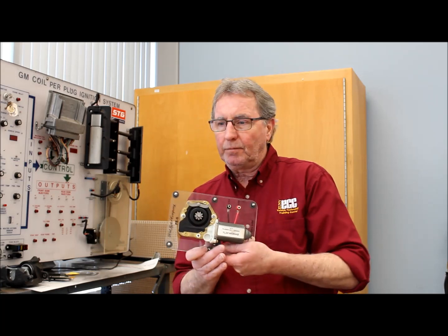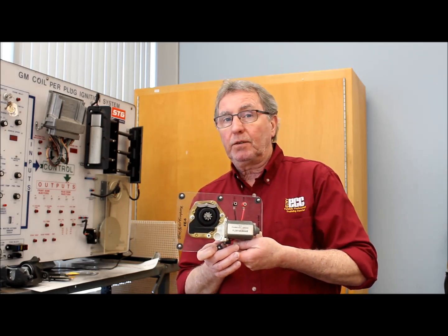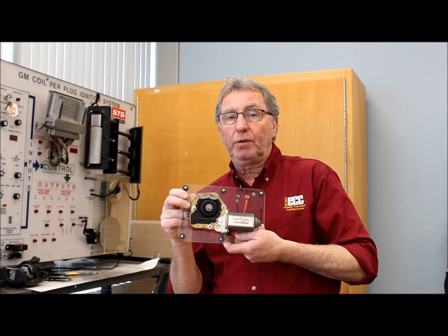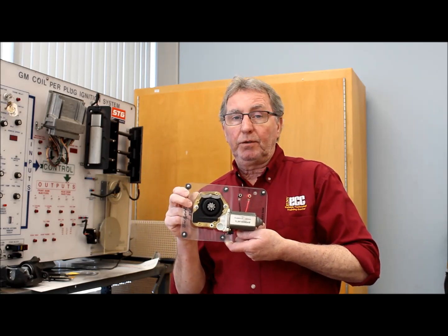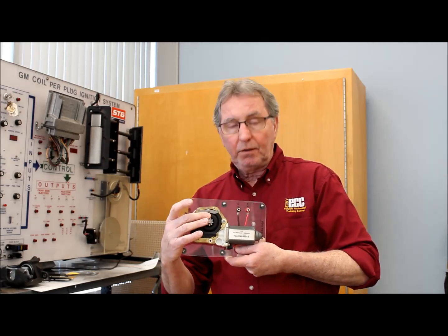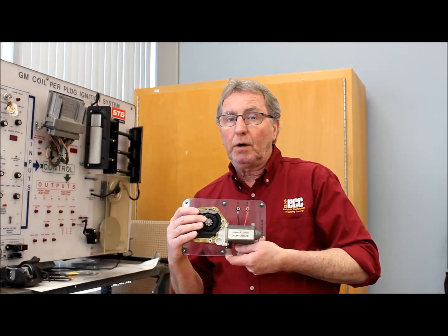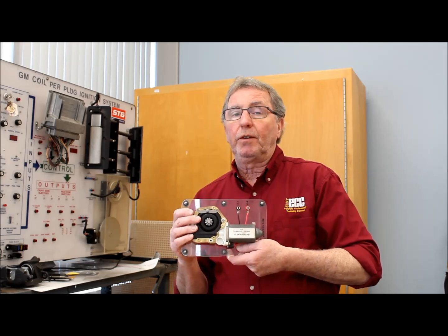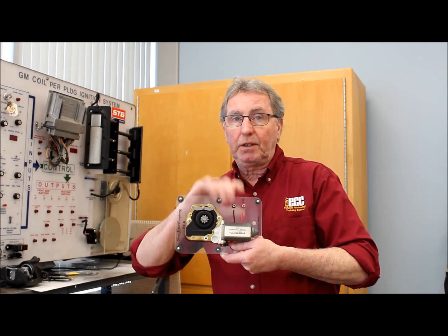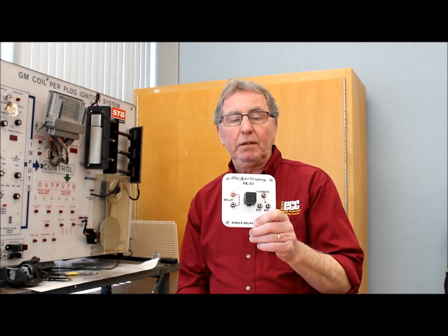This motor, no way. This was 3.5, 4 amps. You try to control this directly through a computer, the circuitry inside the computer is too small to handle this kind of current flow. When this motor has a load on it, like when it's trying to pick a window up or down, it's going to be way more than 3.5 or 4 amps. So how does a computer control something like this? We have this go-between, this relay.